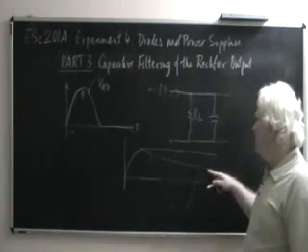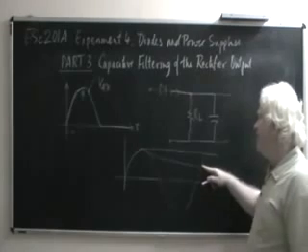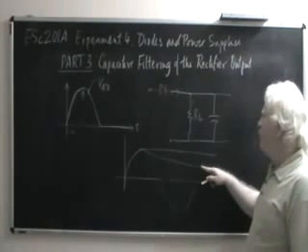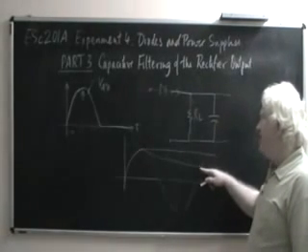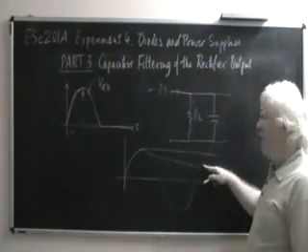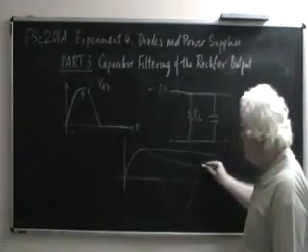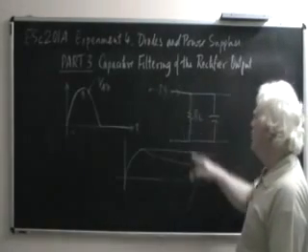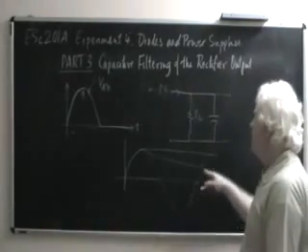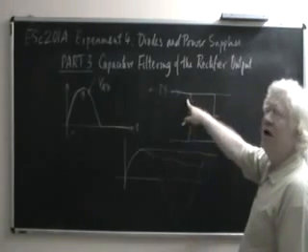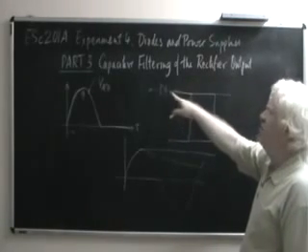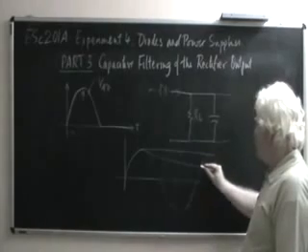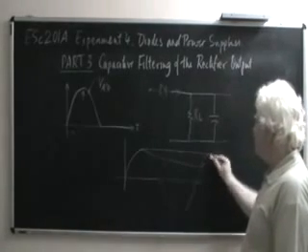At the instant when the rectifier input voltage exceeds the capacitor output voltage, this capacitor now starts charging once again, because the diode is again forward biased, because its cathode end is at a lower voltage than the anode end, so it starts charging once again.